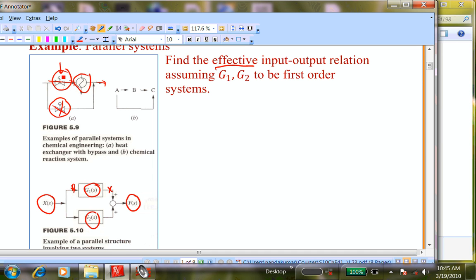But this is just an example of where you might have it, but your question is legitimate because when I'm trying to write an effective transfer function, the second transfer function here is not really active except setting a certain level. So it's going to be maintained constant. It's not going to introduce a lot of dynamics into the process, except when I make a change, the dynamic interaction will be there.